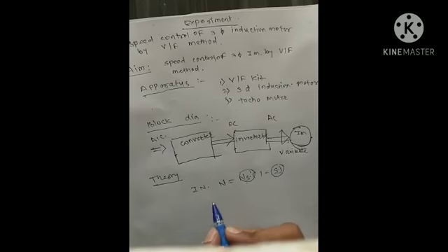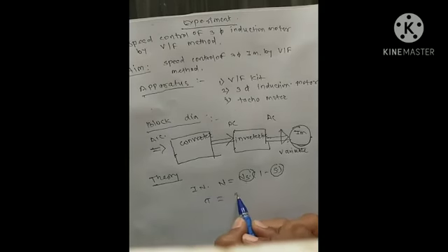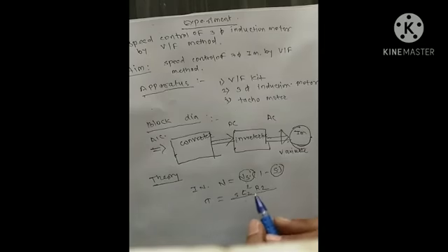The torque is given by tau equals s E2 square R2 upon R2 square plus (s X2) whole square. If the motor parameters R2 and E2 are changed, then to maintain the same torque, the motor reacts by changing its slip. So effectively the speed N changes.